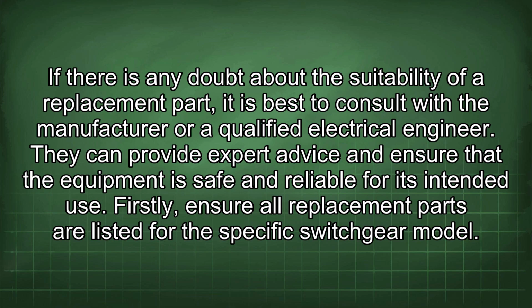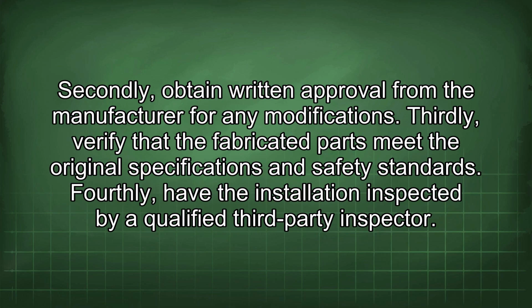Firstly, ensure all replacement parts are listed for the specific switchgear model. Secondly, obtain written approval from the manufacturer for any modifications. Thirdly, verify that the fabricated parts meet the original specifications and safety standards. Fourthly, have the installation inspected by a qualified third-party inspector.